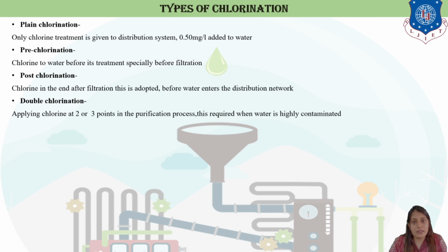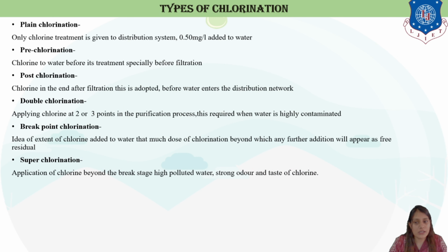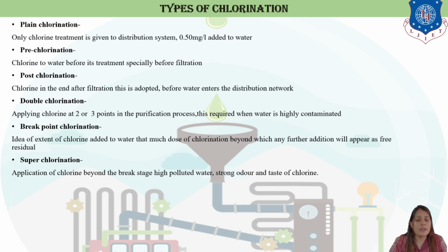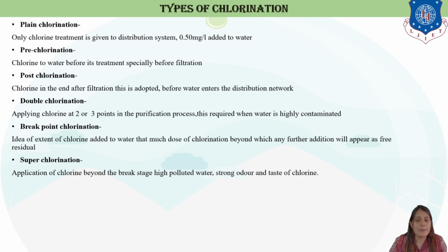Last is superchlorination. What is superchlorination? It is the application of chlorine beyond the break stage, used for highly polluted water, with a strong odor and taste of chlorine.